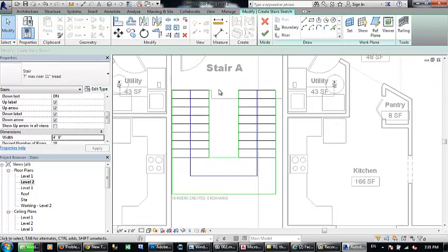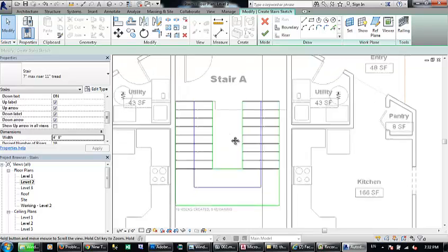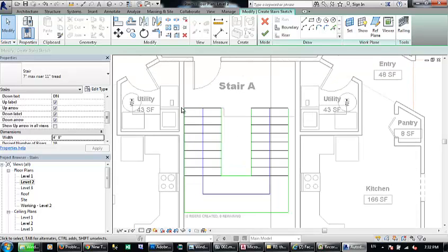So let's see what the green lines mean. The green lines mean the boundary of the stairs. The boundary of the stairs shouldn't be closed. Most beginners close this green line with this green line by a line here. This is wrong, because the risers themselves have to be in black color. So each riser here is drawn in black. The path direction is drawn as a blue line.